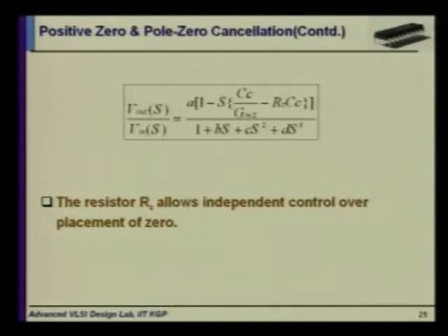So right now where are we? We have retained the advantageous part of Cc. That means the phase margin is not affected by the new introduction of Rz. The feed forward action has been removed by introducing Rz, that nulling resistor. Introduction of Cc gives rise to a new zero, the right half plane zero, and we have removed that by introducing the nulling resistor Rz.